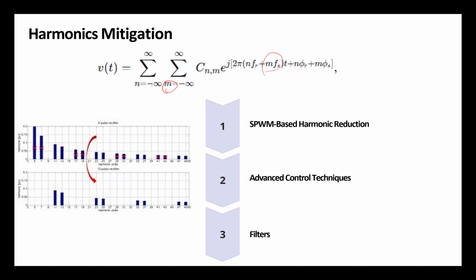frequency. So basically, with the harmonic techniques, you could target a specific frequency to eliminate, and then you have less harmonics. Then you put these lesser harmonics into the filter and you damp them to the level that now it's okay, I can tolerate that level of harmonics. Make sense?